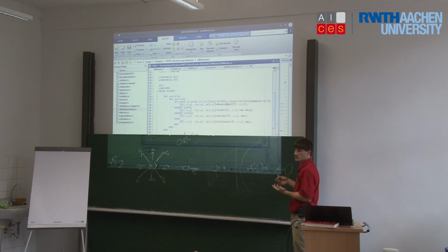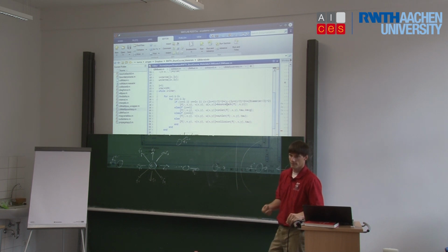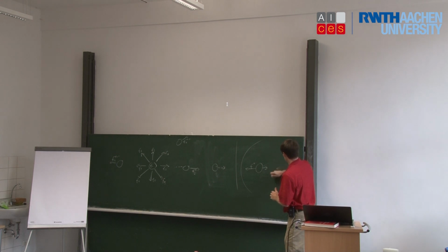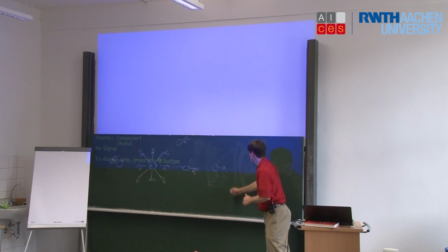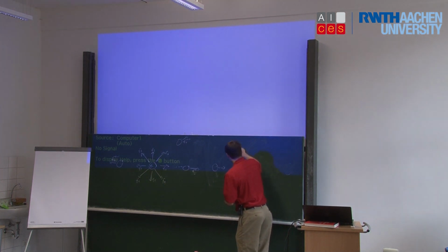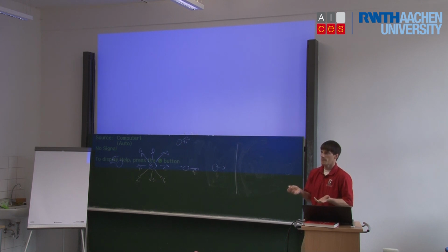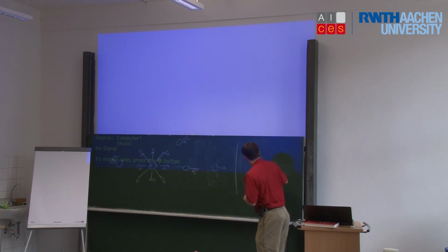So you're doing interpolation, and at least the Lattice-Boltzmann literature displays it as a second order accurate boundary representation. Okay? So that adds a little bit more detail or accuracy on our boundary. The second thing that we want to know, we want to be able to evaluate the drag. Okay? So if we have our ellipse, we want to know what is the force that's acting on this ellipse. Okay? Well, what happens here?